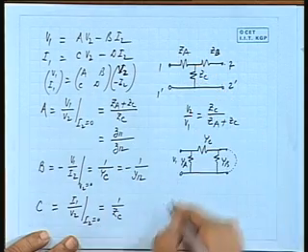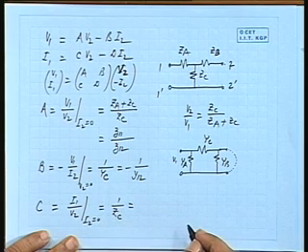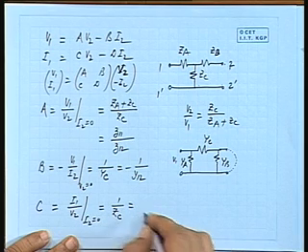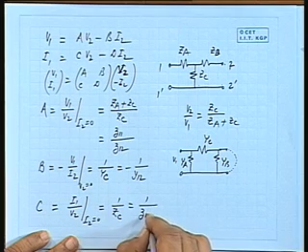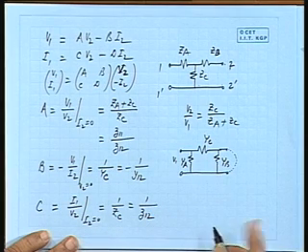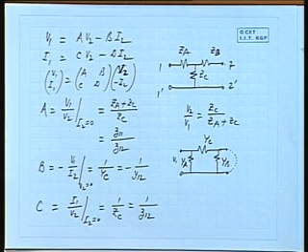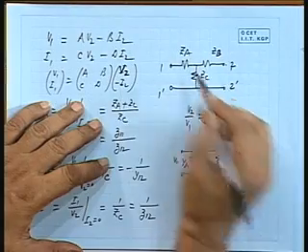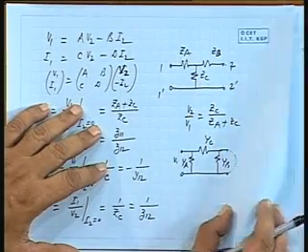And what is ZC in terms of Z parameters? Z12. You remember, whenever we have open circuit parameters, we will refer to an equivalent star, T connection. Whenever we have short circuit parameters, we will immediately refer to a delta. Then it is easier to link up Y11, Y12, Y22, similarly Z11, Z12, Z22. In terms of these, I can immediately write.